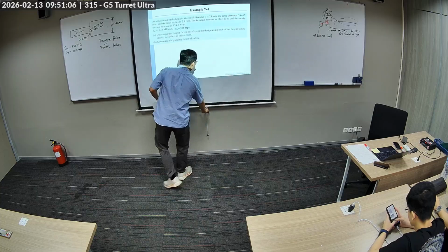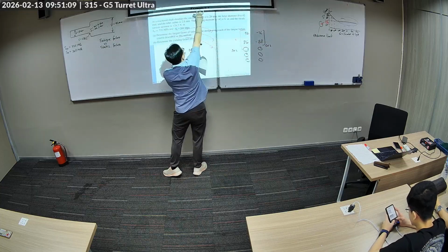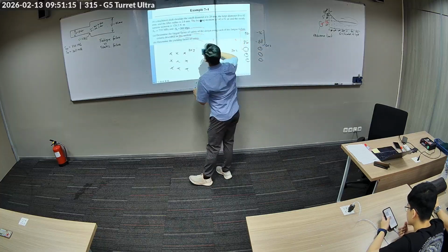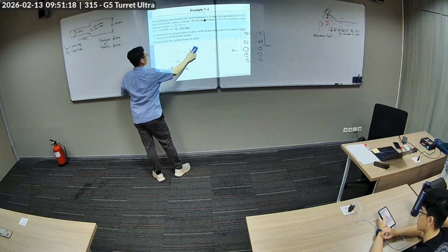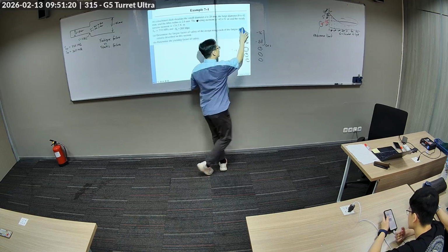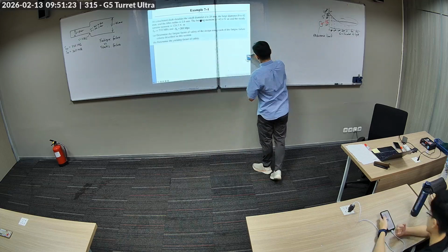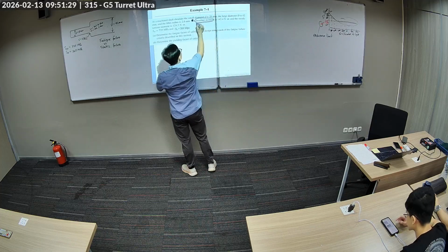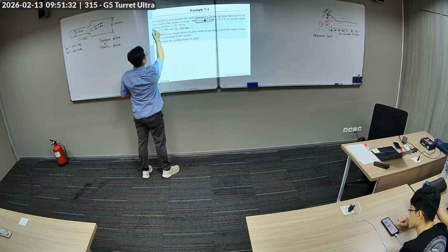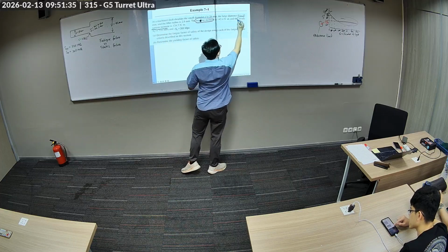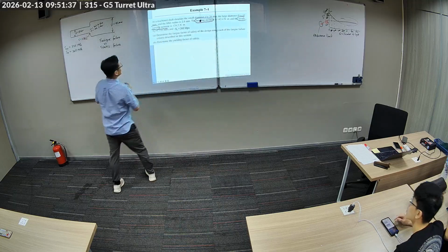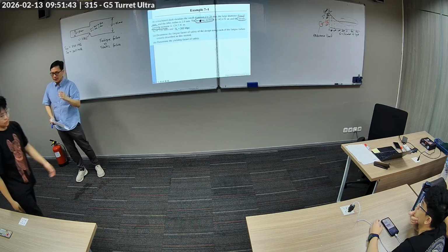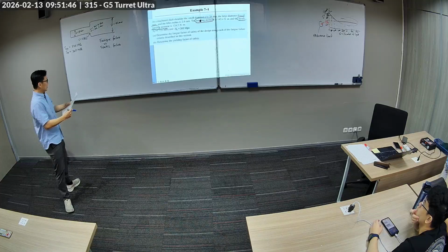Now notice that we have a bending moment and we have a torsion. I want to again remind you: bending moment and torsion, steady torsion. Why does it say steady? Well, that means my torsion is not cyclic. What is cyclic here is bending.